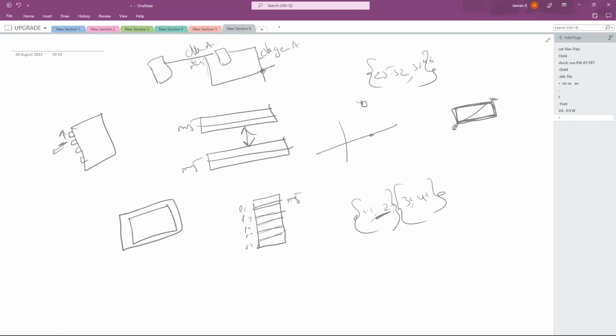For example, if you allow the metal layers over this macro, it will be shorted, right? Say some metal layer is going on like this, some VDD/IO is going on like this, but this pin is VSS/IO. That is a short circuit, right? So by default we will be seeing some blockages over the particular macro. Till M5 we have the blockage for this macro.